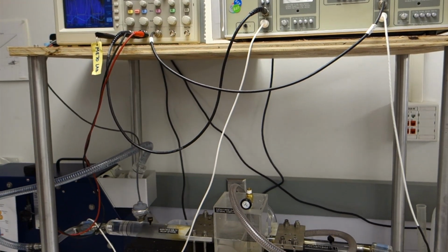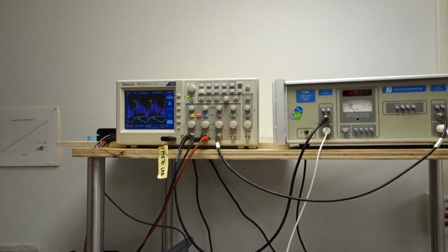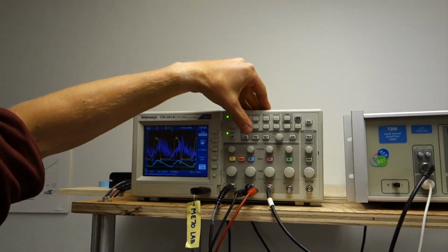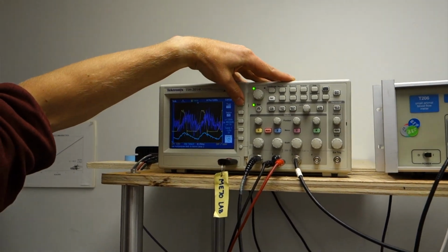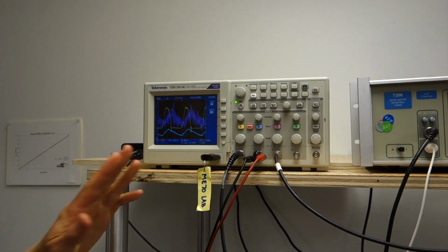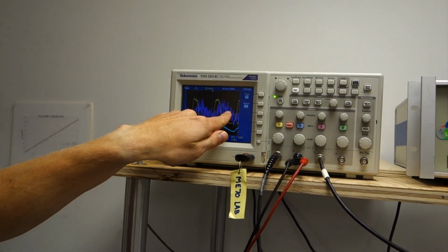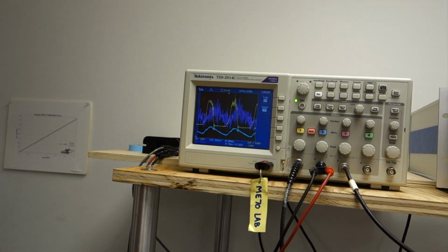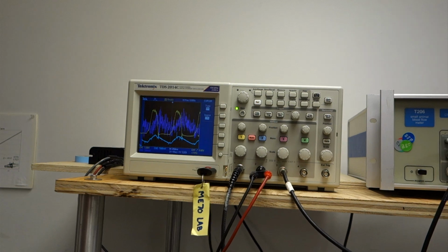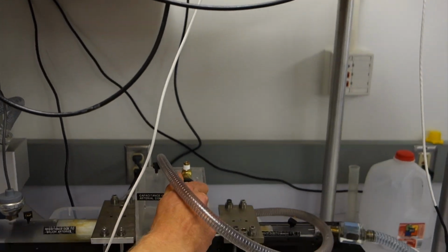It's not bad. Our oscilloscope is wacky here, so I'm going to, oh, it fixed itself. I'm going to turn my cursors off just for kicks. Type off. There we go. And remember, just so we're explicit here, Q1 is yellow, P is blue, and Q3 is purple. Now, to decrease capacitance, I know that the expression for capacitance is the volume of air over PATM. I'm going to decrease the volume of air by opening up the valve.